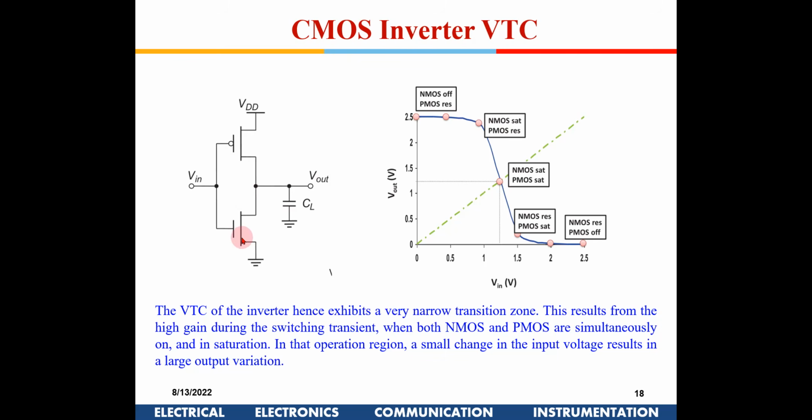Initially what happens is this is switched on, right? Whereas this is trying to charge the node, this is trying to discharge the node, but obviously you are giving a small Vin, so this will not be able to pull the charge to zero. It will not have adequate current carrying capacity to pull it down because of lesser overdrive voltage.